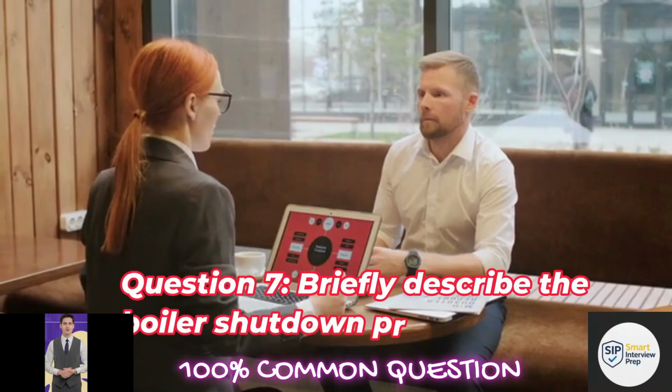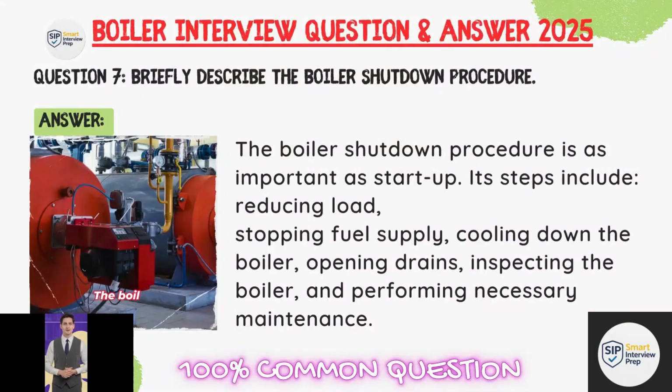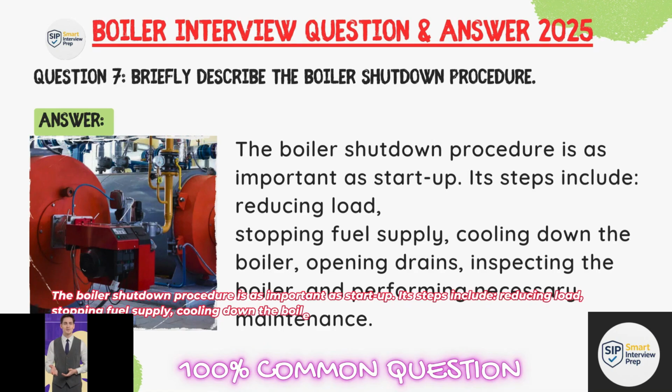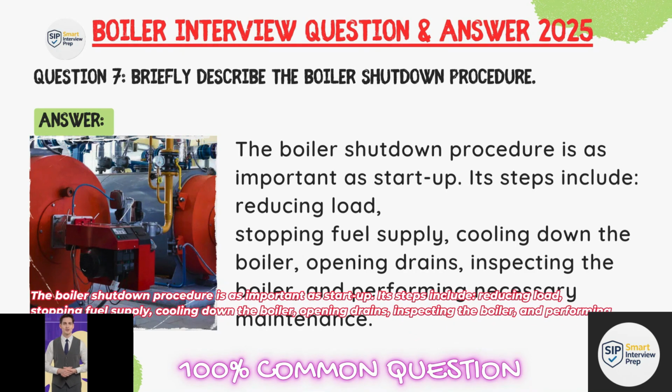Question: Briefly describe the boiler shutdown procedure. Answer: The boiler shutdown procedure is as important as startup. Its steps include reducing load, stopping fuel supply, cooling down the boiler, opening drain, inspecting the boiler, and performing necessary maintenance.